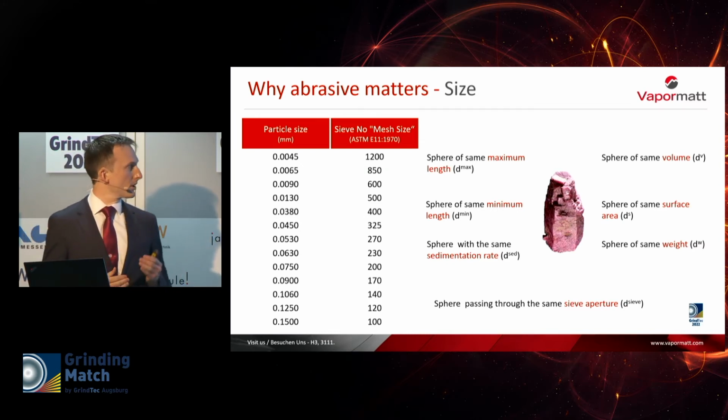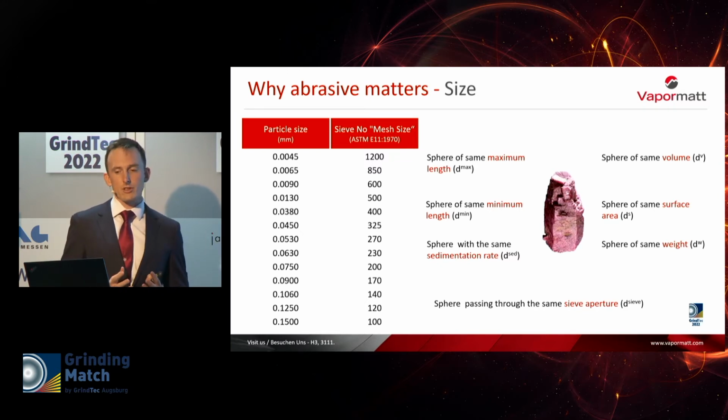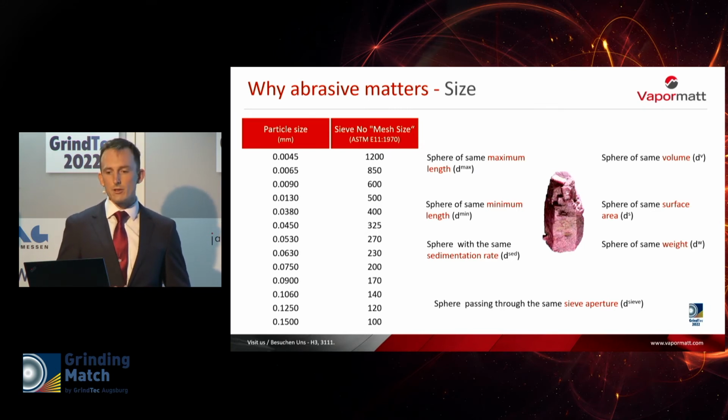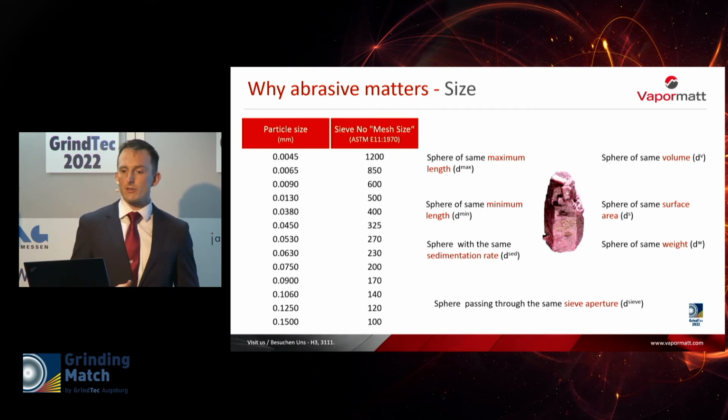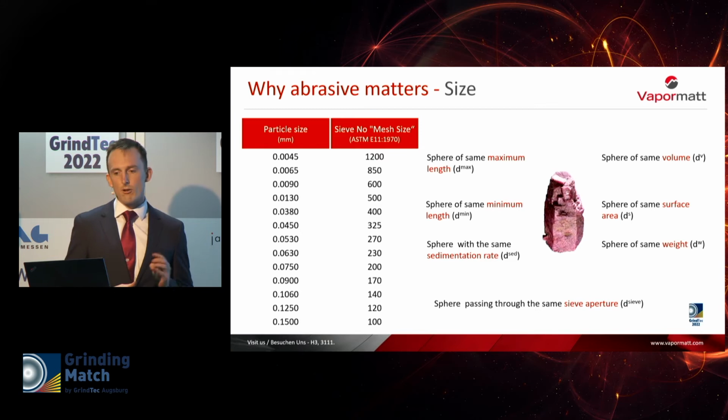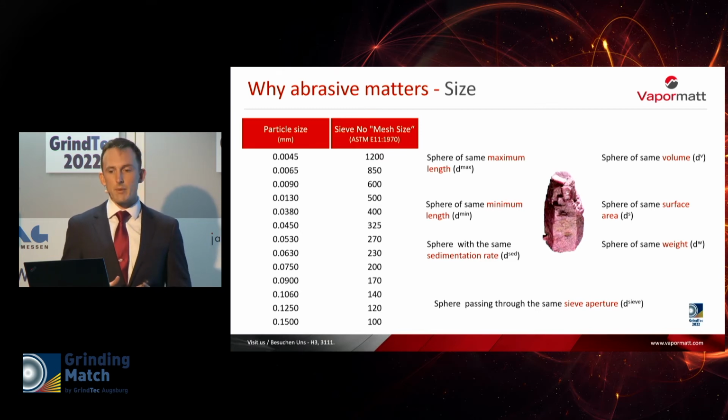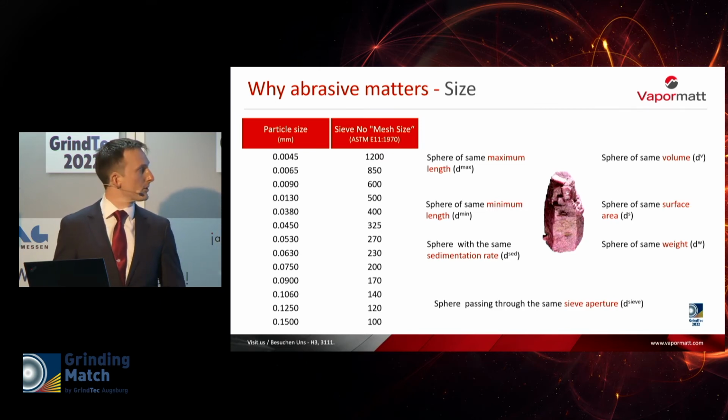In the past, it had become common to use mixtures of sizes, for example, a 180/220 mesh or a 220/240 mesh. However, the shift is moving back to one size only because that's giving a better consistency of processing. It is common for tooling manufacturers to focus on something maybe around 150 or 220 mesh for edge honing, and perhaps 320 or 400 mesh for post-treatments.